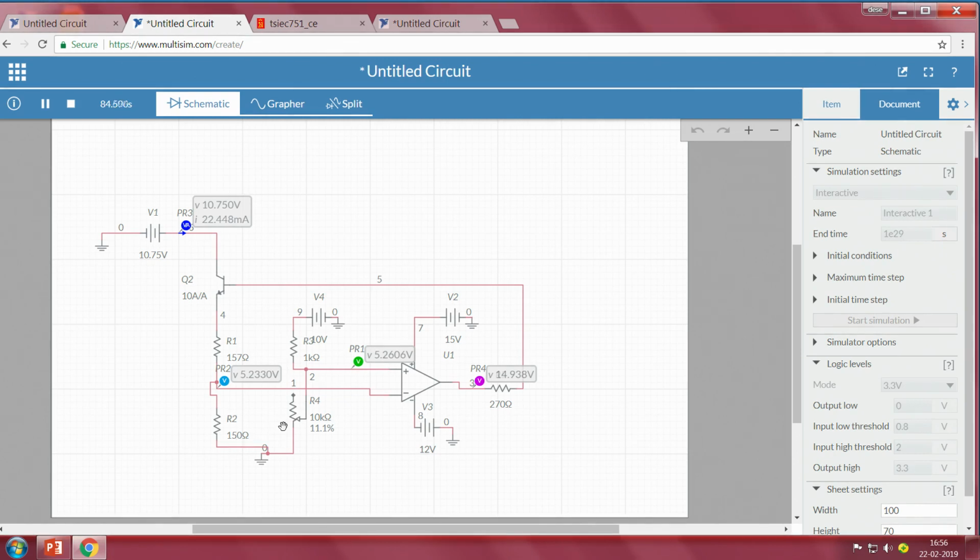The room temperature could go as high as 40 degrees or as low as 10 degrees. However, this part of your bridge should always maintain a constant temperature. How does that happen? You can maintain the constant temperature at 150 only when you are able to control the resistance of this bridge. Now how are you able to control the resistance of this bridge? Because of the feedback mechanism we have here.